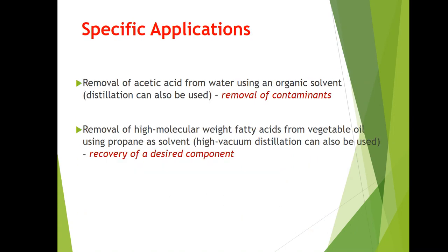Now, as to specific applications of extraction, it could be applied in the removal of acetic acid from water, using organic solvents. In this case, distillation can also be used, but in some cases they prefer extraction because distillation is highly energy intensive.